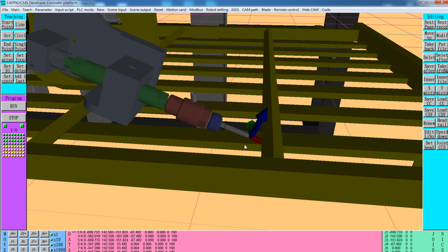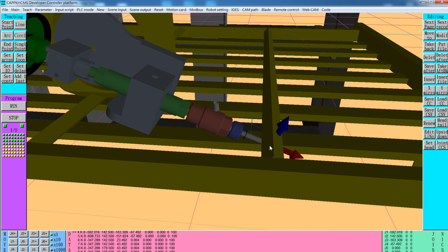The third line is turning the tool inclined, and move to the line 4th. You can see the line 4th is the starting spot welding. This tells us the line 1 to line 3 is the leading tool path, while the 5, 6, 7 is the retracting tool path, similar to 1, 2, 3. So 5, 6, 7 has to be removed, and the second 3 has to be removed as well.